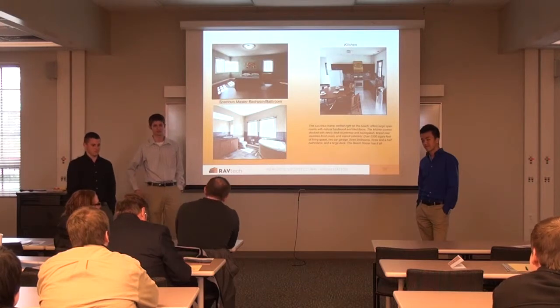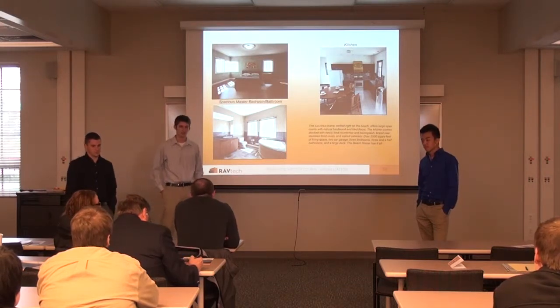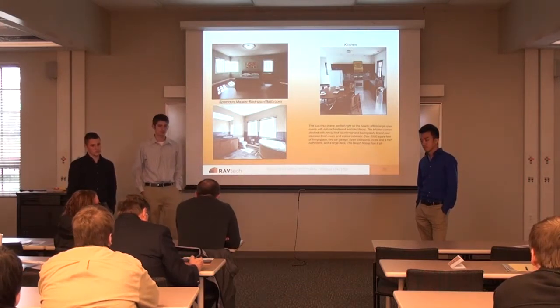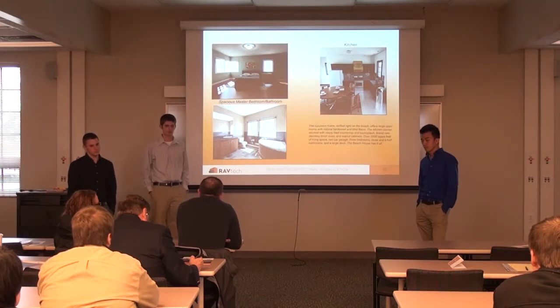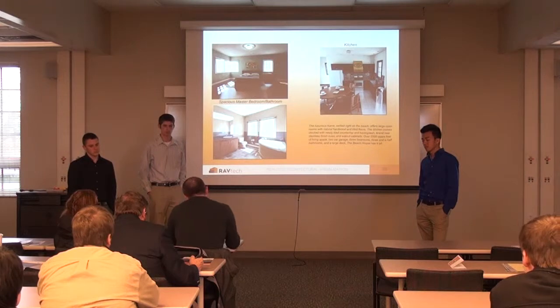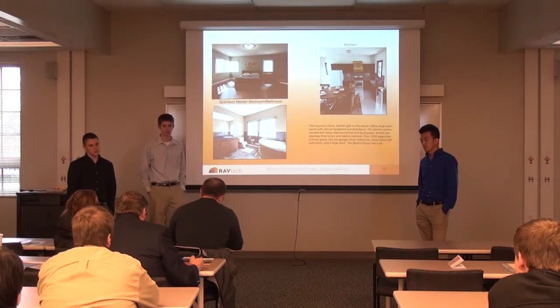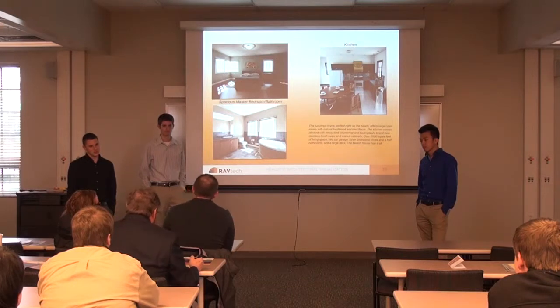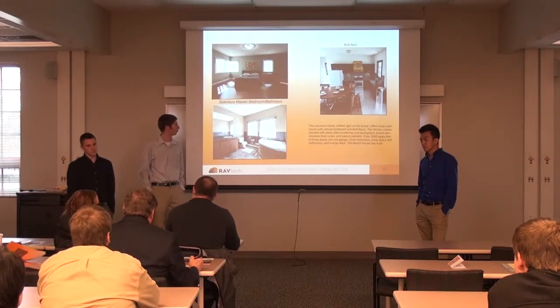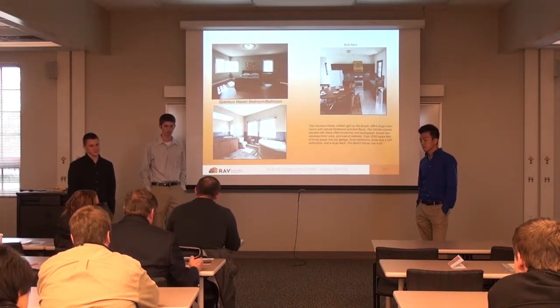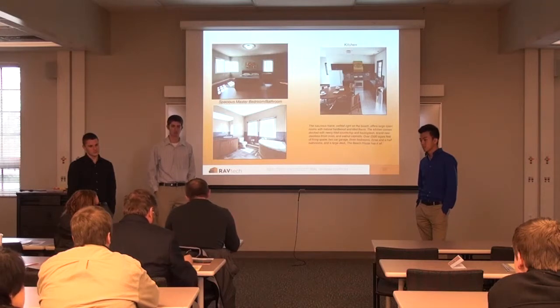So you talked about the materials in Revit, and I know at our company the Revit team doesn't necessarily care about materials in the initial schematic phase. When you're doing a 14,000 seat arena, the problem is when I get the model, it's all generic. It's always a pain to connect everything together because either I get one massive clump of geometry with all the walls and windows, or I have 107,000 pieces in there.